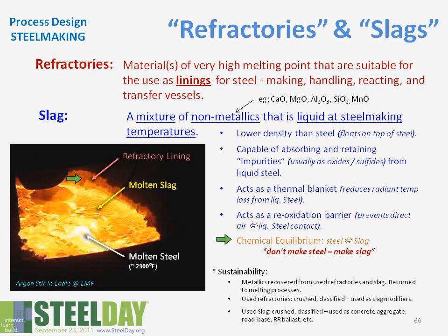There is a chemical equilibrium between steel and slag. I was taught in metallurgy school that you really don't make steel, you make slag. The analogy there would be a flywheel. The slag has the chemical mass. You must act upon the slag, because if you don't, it's going to pump things back into the steel.